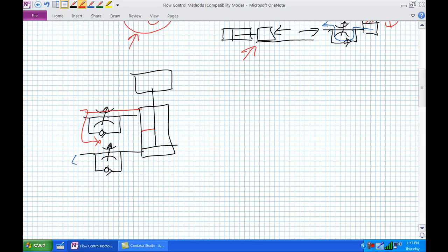And it's going to go so fast, it's going to leave that fluid right there behind as that drops into there. I know you're controlling the rate of fluid going into there, but that doesn't matter, because that piston face is already slammed to the bottom, because that pressurized fluid here has no pressure or very limited pressure and it can't hold it up. What's going to happen here? You've developed a vacuum, and these things are going to enter an atomized or a gaseous state. Basically, this is a cavitation event. Okay?